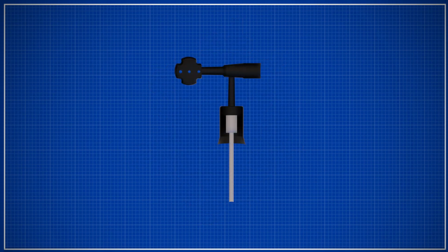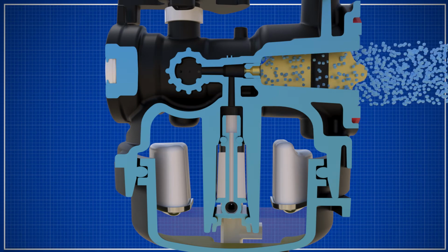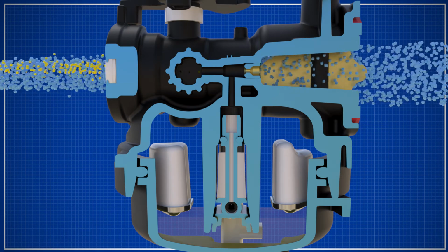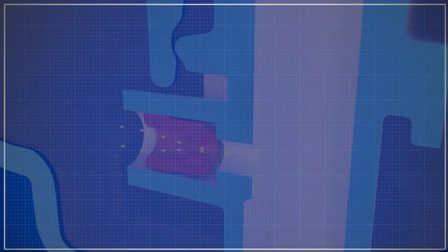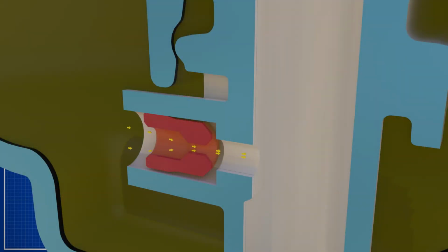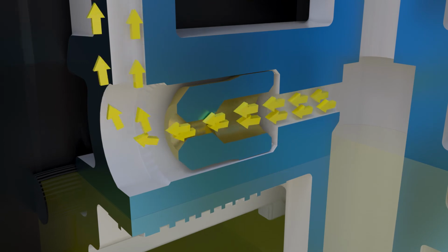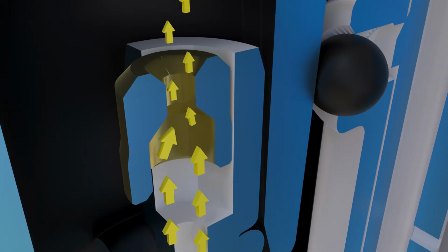With the knowledge we learned, let's take a look at carburetor circuit operation. Let's start with the idle circuit. It is important to know not all carburetors have idle circuits. These types of carburetors are used in smaller machines like lawnmowers. The fuel source for the idle circuit is metered 2 times. The first stage is through the main jet in the center leg or bowl nut. From here, fuel is pushed up a drilled passageway in the center leg and through the second meter jet.